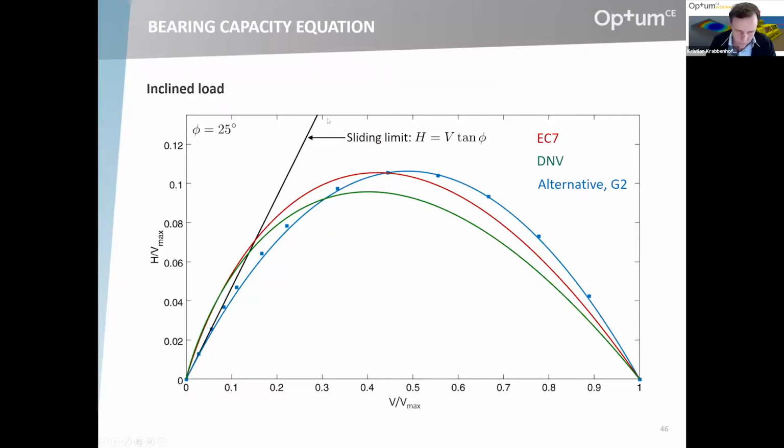there is a limit, right? And you might as well build it into the inclination factors rather than having to check everything is okay as well. But you cannot get past the black line, and I was quite surprised when I started looking at the codes that those inclination factors, if you look at the NAD of Eurocode 7, this is what is given, and it doesn't say anything about having to check for sliding.